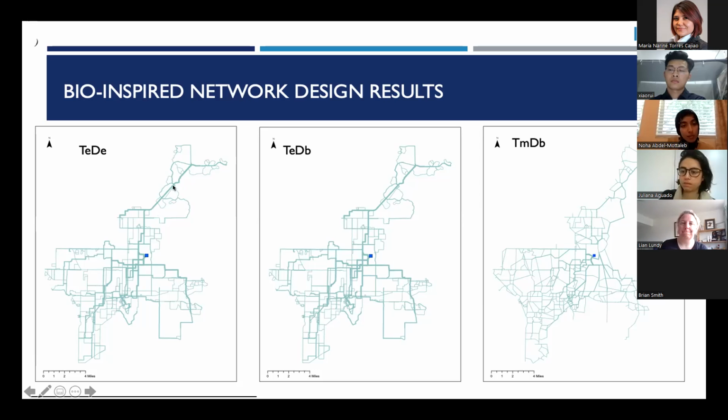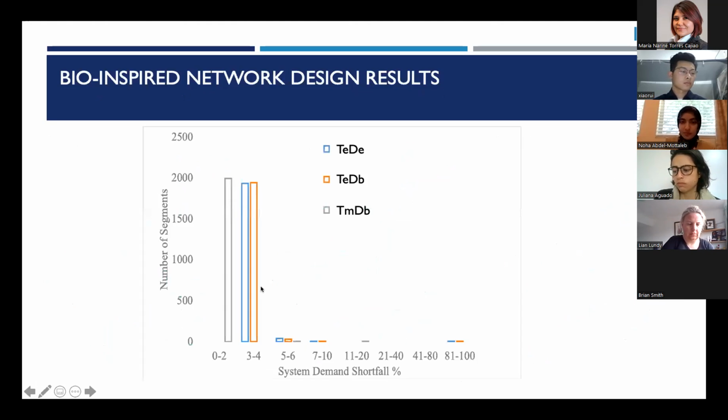So simple observation, but also we plotted the diameters on GIS, and here the thickness of the pipe or the edge represents the diameter. And so something that became clear is when we have the forward model connectivity, we see that the pipe diameters actually change more gradually. And so that's an interesting finding, whereas we have more abrupt changes in diameters for the empirical connectivity.